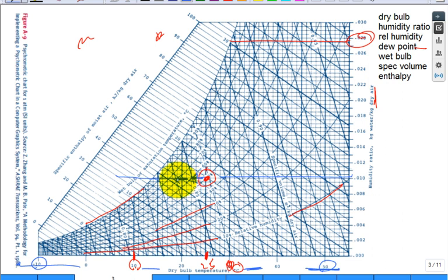Now, if I move to this point right here, my dry bulb has dropped, maybe to 19 degrees C. Relative humidity is 70%. See how I'm conceptually playing that game? You keep going until you hit the wall. Now I'm at 100% relative humidity. If I try to cool it some more, I can't do it without dropping omega, meaning condensing. I've hit the dew point. This temperature right here looks like around 14 degrees C, which is my dew point temperature for the air in this room.